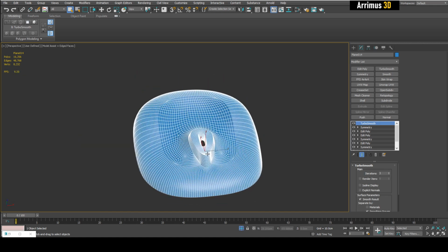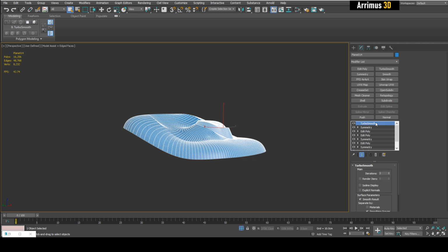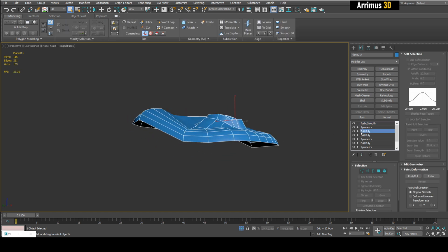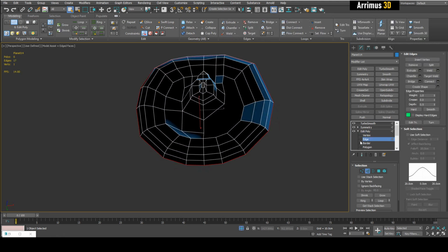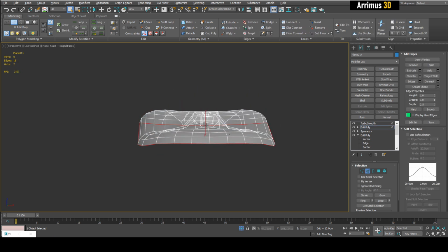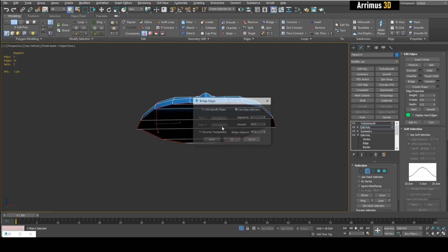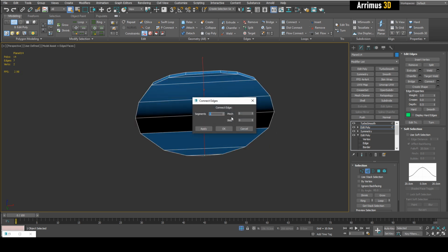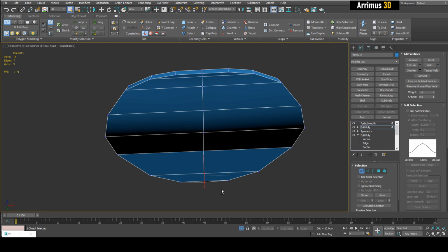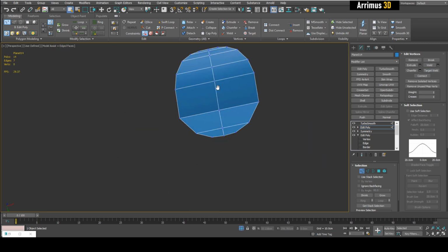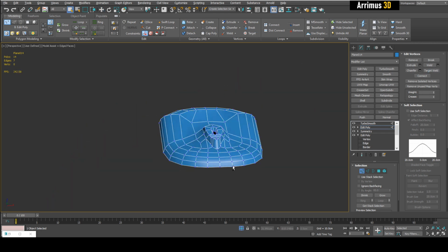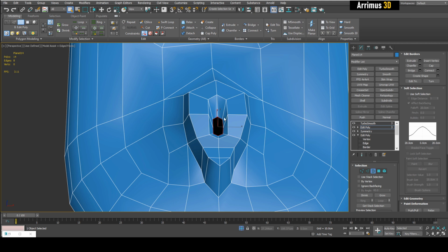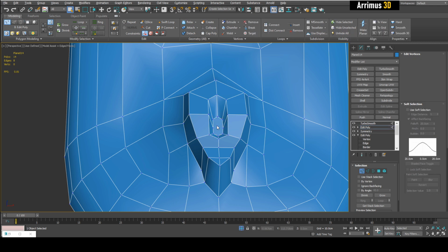So if I was worried about the volume, all I would need to do here is just go into here and then go into edge here. And actually, let's go into the poly on top of that. And so then I would just, for example, deselect the center edges here and bridge this. And then insert a loop through here and then just weld that. Target weld, making sure it's closed up. And I will go into here as well and then Alt P to cap this as well.